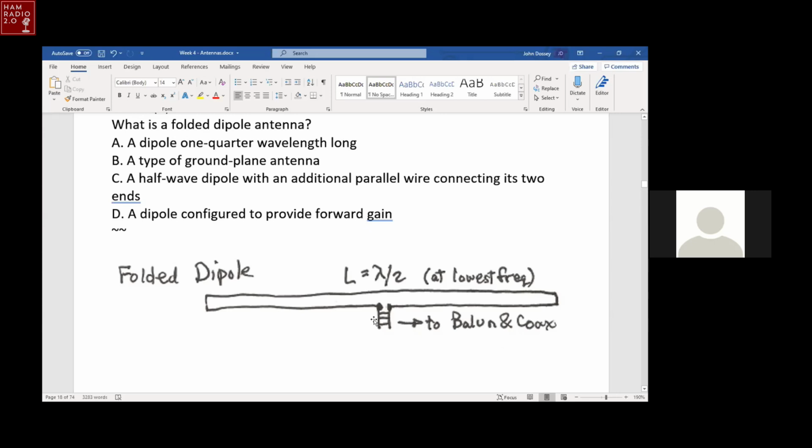But a folded dipole is where you put another wire in parallel with the 2 quarter wave dipole wires, connect them at the end, and the longer wires connected here across the feed point, and it works just great. I've built several of these for various frequencies. One field day, I built one for 10 meters, and we got out like gangbusters on 10 meters with this folded dipole. And some other details to it, but that's covered in transmission lines.